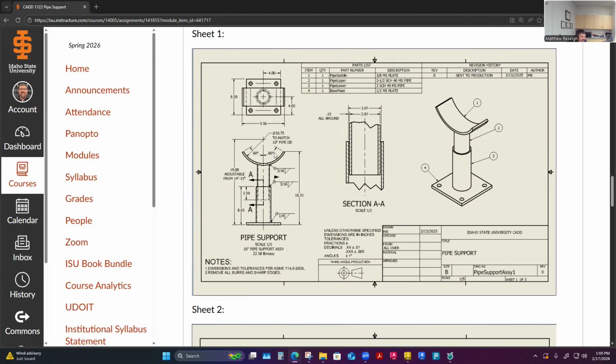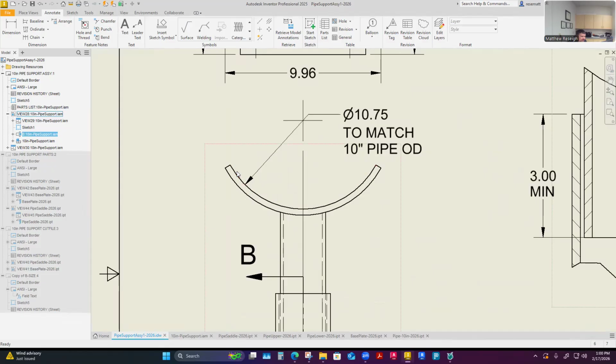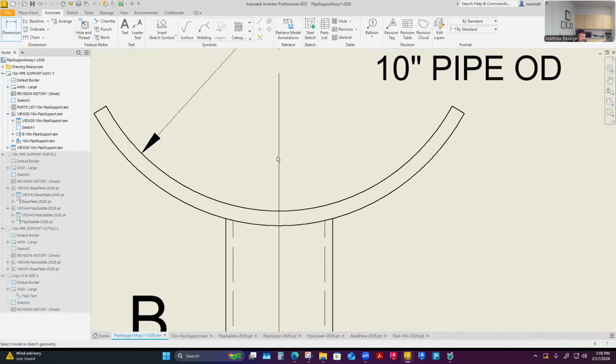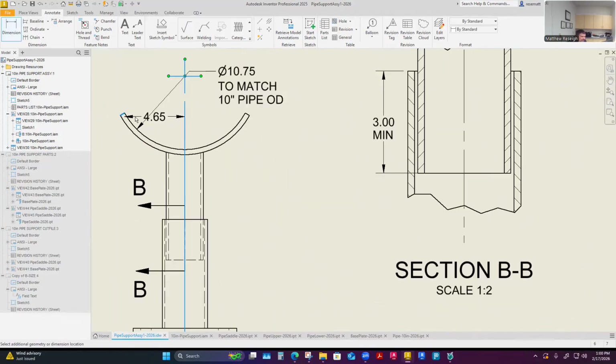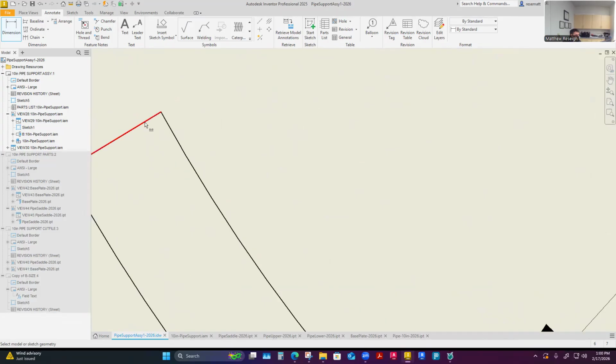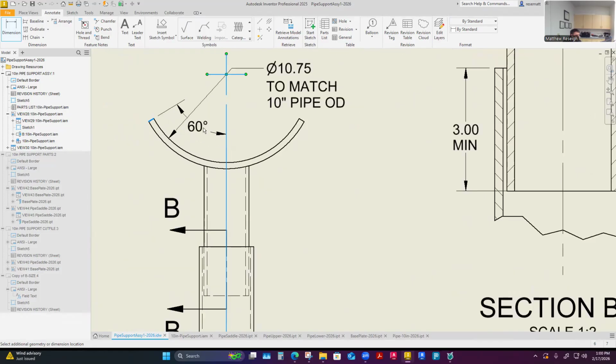So this one, and they have some 60-degree marks there. Those shouldn't be too hard. This is one where you start to get picky on whether you're picking points or midpoints or lines when you're doing your dimensioning. This 60, I don't think works well if you go like here to a point. It wants to pull that as a linear dimension. Maybe I could choose angular, but I don't think it gives me the option. So the dimension that works best here is to say it's actually this line and how it lives in space, not a point on it. And then this particular dimension here.